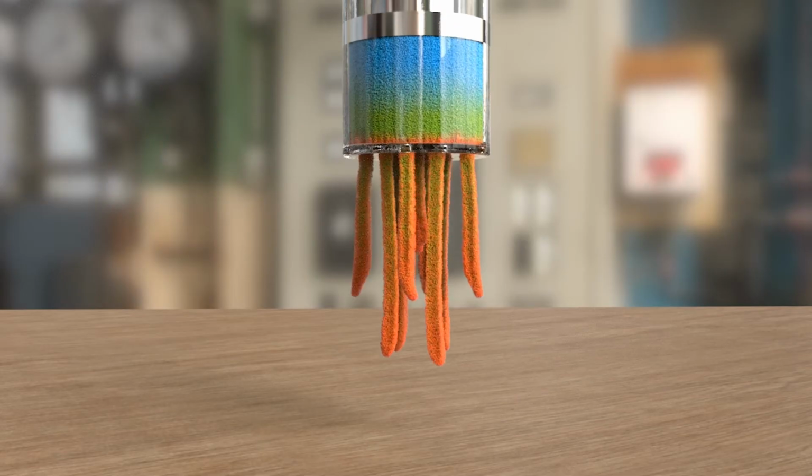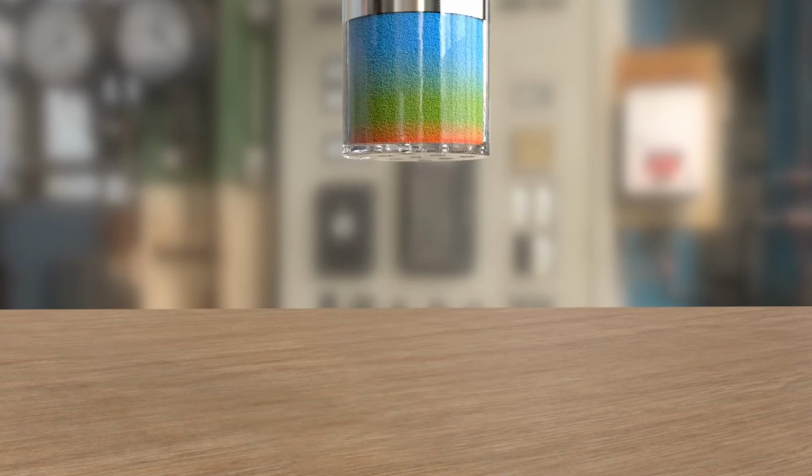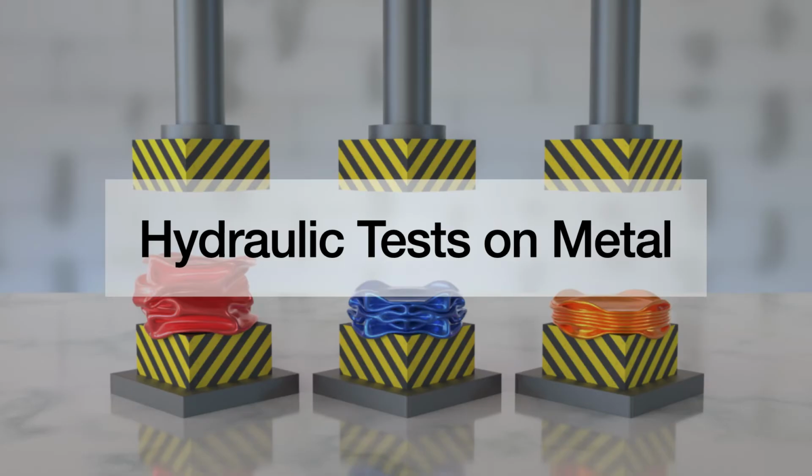Leveraging MPM's automatic handling of topology changes, we simulate Play-Doh modeled by von Mises plasticity pressed through a cylindrical noodle mold. Our variational plasticity model is independent of spatial discretization. The following examples are simulated with the finite element method with the incremental potential contact model.